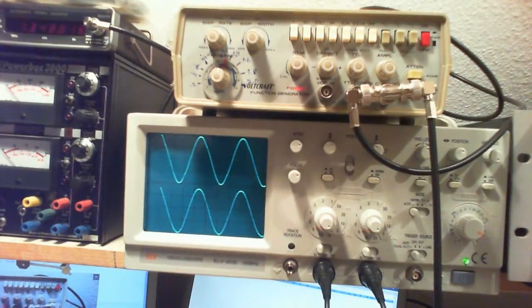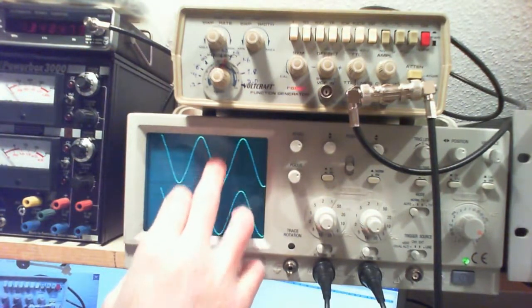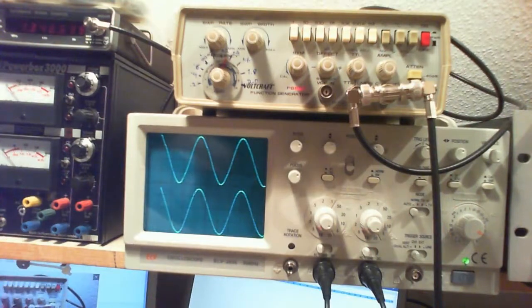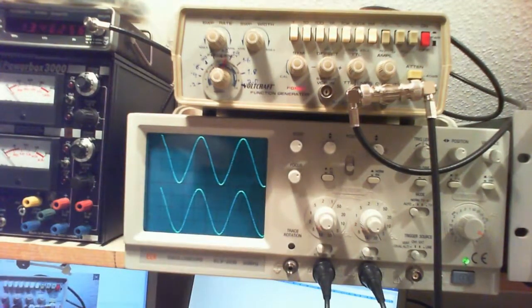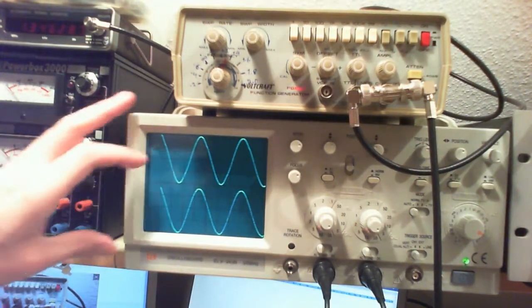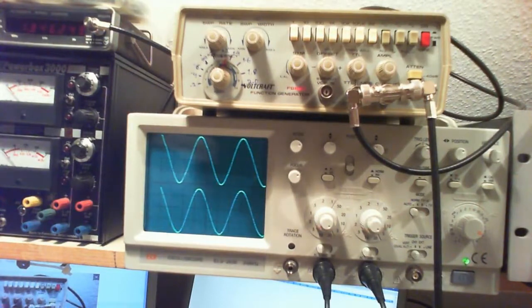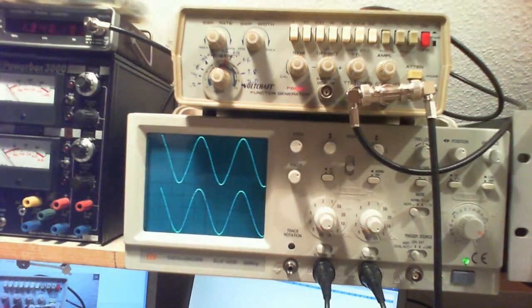Now if I increase the frequency, you see that my input starts decreasing as well, and that's just related to the signal generator, and has nothing to do with this experiment. Meaning that if you watch the output of the signal generator connected to nothing, just to the oscilloscope, you will see the same thing happening.